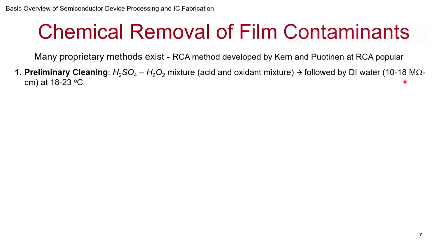18 mega ohm centimeter is usually the unit for resistivity, and that value is usually considered to be good quality DI water. Anything above 10 to 18 may be okay. Of course, you have to try your best to keep it as close to 18 or at 18. And usually it is done close to room temperature, 18 to 23 degrees.